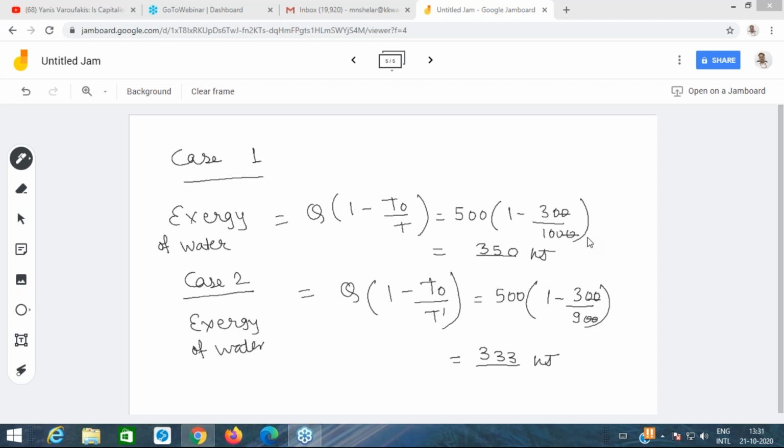Okay, destroyed. And why is that exergy destroyed? The exergy has been destroyed because of irreversible heat transfer. Now suppose, yeah, correct. That is correct, Tanaya. Now suppose you increase the irreversibility. So how do I increase the irreversibility? Suppose I want to increase the irreversibility. Suppose case 3 you consider where there is more irreversibility.